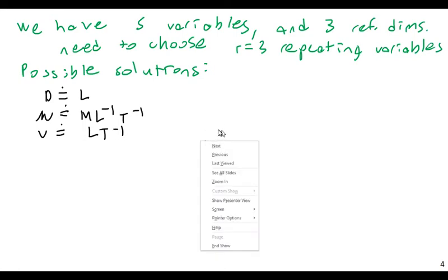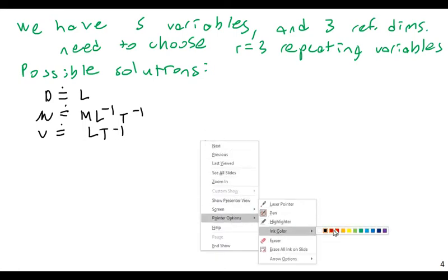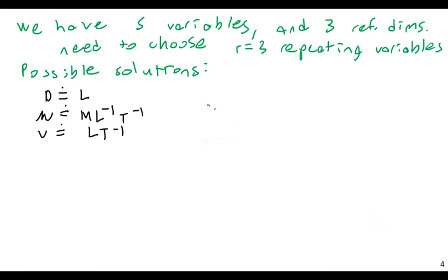Well, let's look at this. We have the 3 conditions previously. So the first question is, did we use the dependent variable? Well, we didn't. We didn't use delta PL, so that's good. All reference dimensions are present, so we got an M, L, and T. That would work. And there doesn't appear to be any way I can combine these to create something dimensionless.